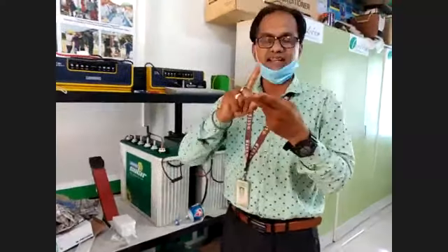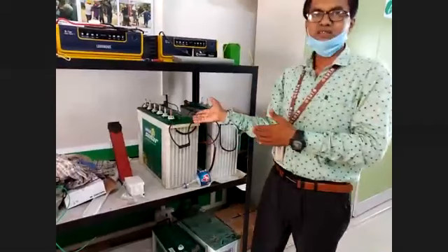As per the calculation, you multiply 8.36 by 3, that is 24 point something ampere. Though 15 ampere current is required, almost the maximum current is flowing from the panel, that is 24 ampere. So easily the battery is charged.